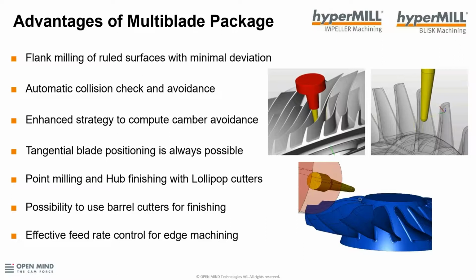Blade numbers also have a major role to play for the passage width, as we know. So it is very important to find an optimum toolpath without collision with these blades, which hyperMILL can actually do automatically. So that's a huge help, part of 5-axis simultaneous machining. hyperMILL also assures perfect blending between the various sections for long and thin blades.